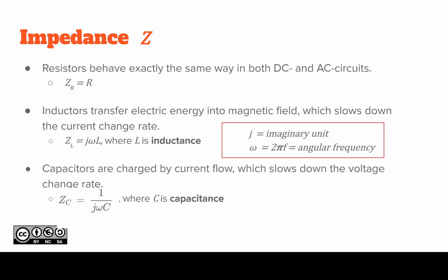That's because it changes the phase by 90 degrees. Practically, what it means is that the inductor delays the signal by a 90 degree angle. So if you have a sinusoid, and the voltage across the inductor is changing, then the current will follow 90 degrees later.